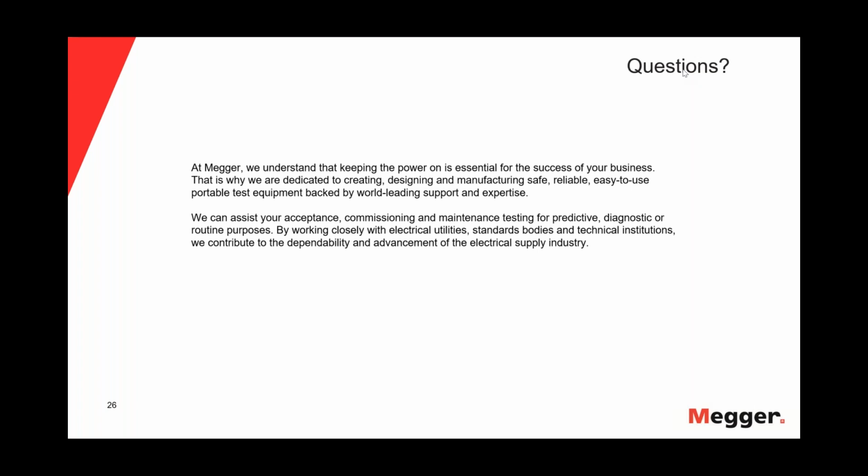In order to get a discharge, you need a high resistance, because otherwise you cannot get a discharge. You have to build the voltage up, and then it basically flashes. So when you have water ingress, that does the opposite. Water ingress basically reduces the insulation resistance, makes it much lower resistance, and in that regard, PD, partial discharge, cannot detect water ingress and cannot detect water trees.